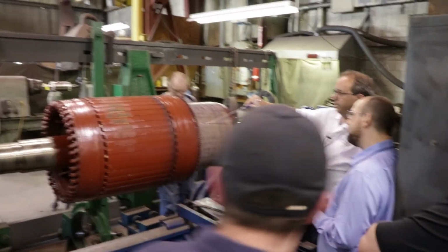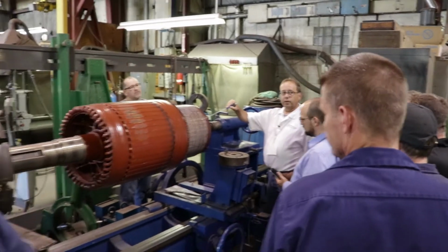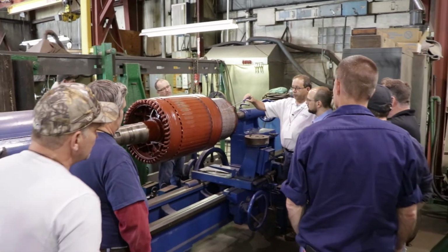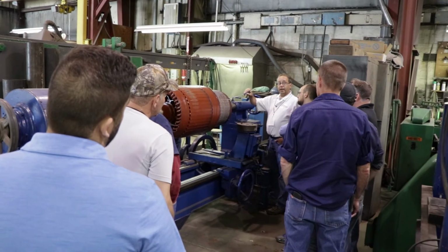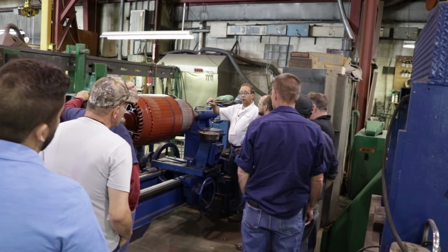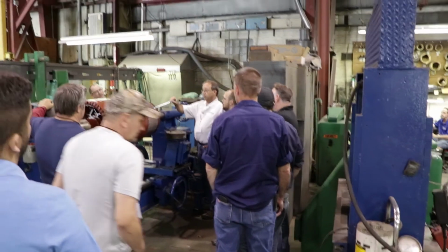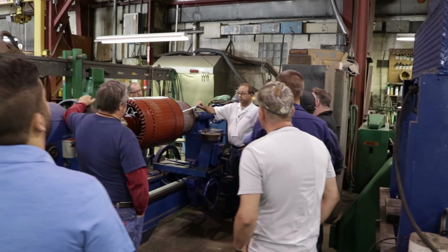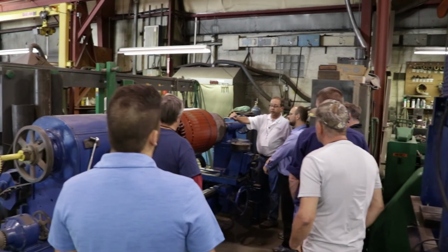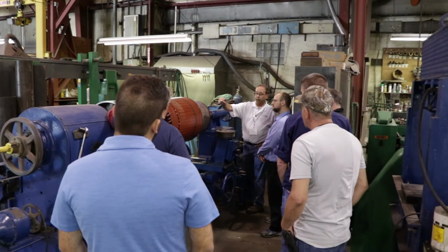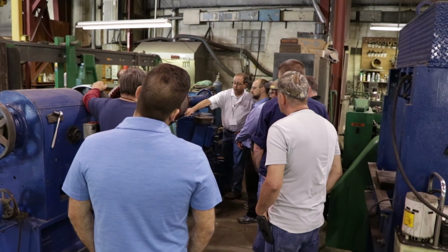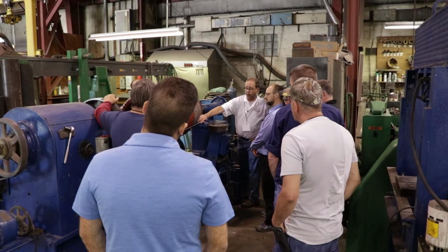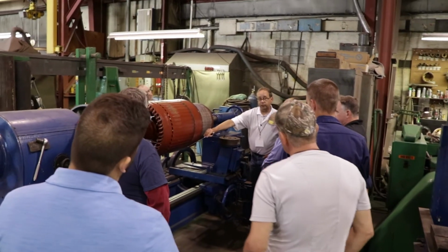Each one of these is a copper segment that is insulated from each other with a strip of insulator that's generally made out of mica, which is an excellent insulator, and it's made from a rock. Each one of these then are in turn connected to an individual coil that will span around, say if there's a 1 to 12 pitch, that coil may span 12 segments.